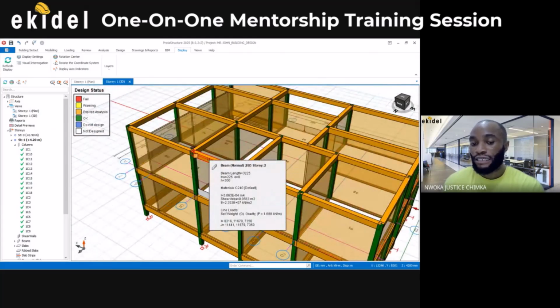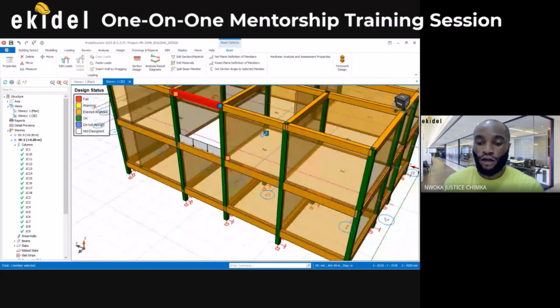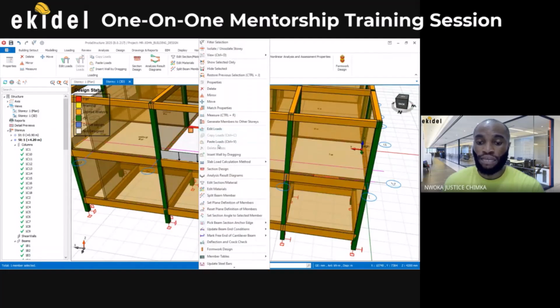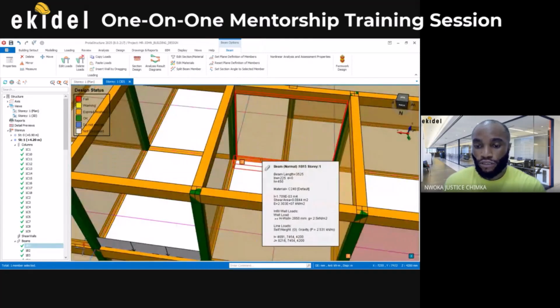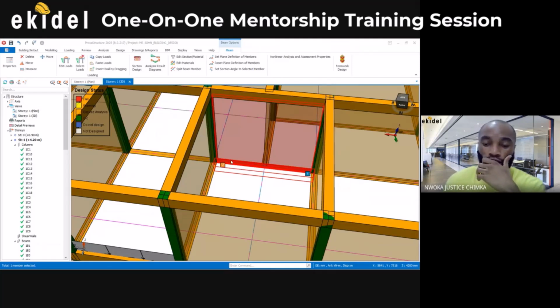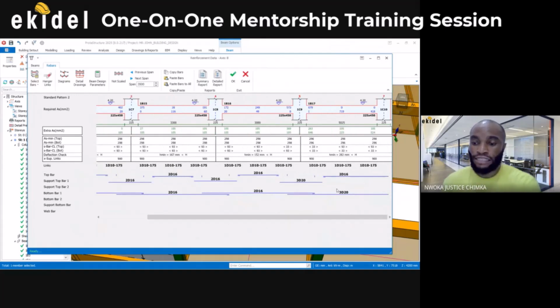Because most times, this can end up giving you, for example, a bigger size of rebar, when you can use a smaller size. For example, let me open this beam that is added, to check what is happening to it. I open this beam, then section design, and they just say okay, and so now you can see that here is giving me 20 diameter, D20.